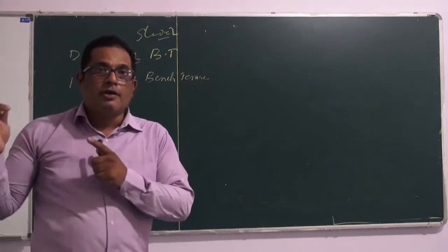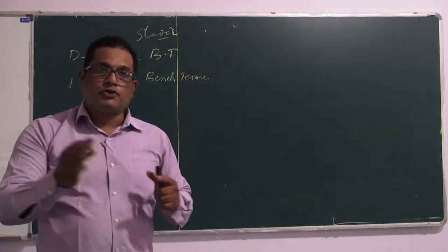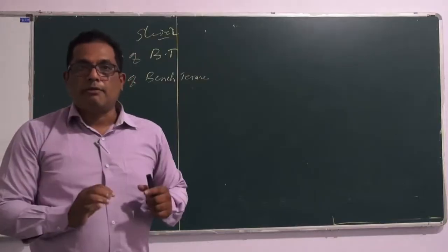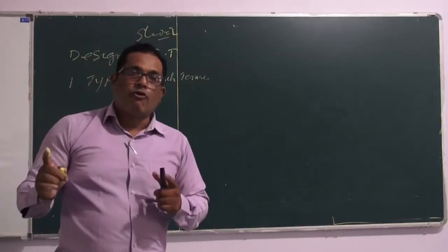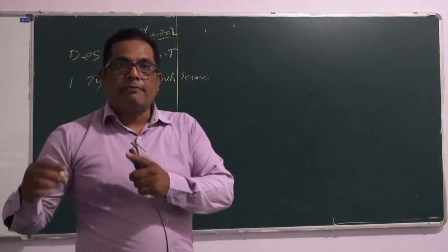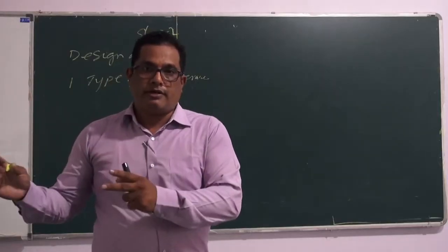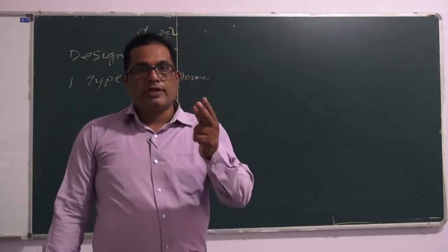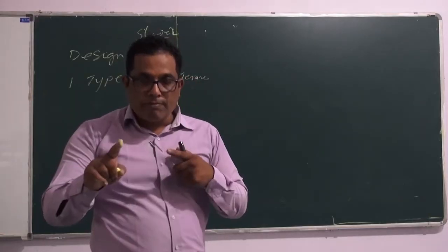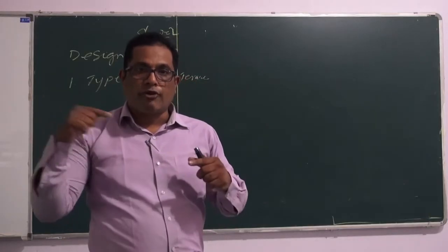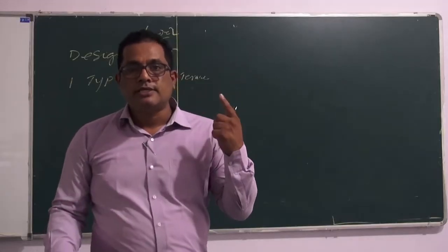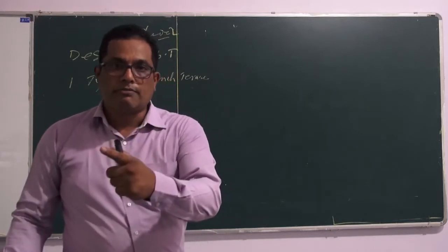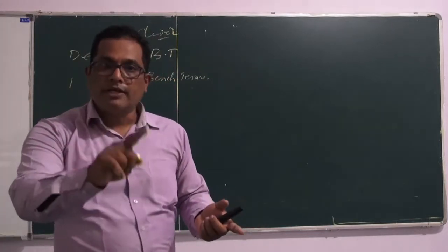Should we go for inward sloping, outward sloping, or level type of bench terrace? That will be determined by the average rainfall of the area. As explained earlier, if the average rainfall is medium, then we go for level top. If it is high, then we go for inward sloping with a channel, and if it is low, then we go for outward sloping with a shoulder bund.